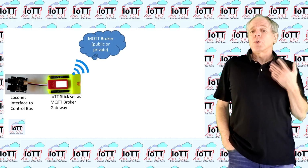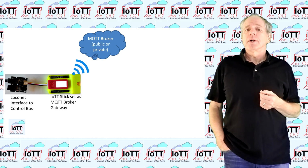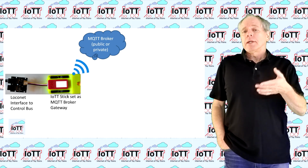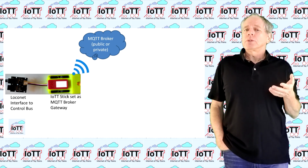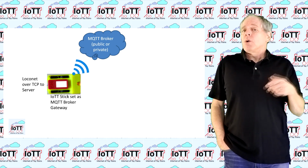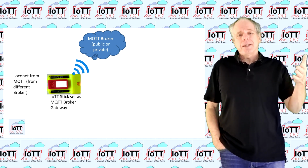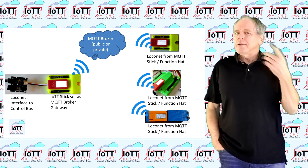The second option to connect IoTT sticks using Loconet is connecting them to an MQTT broker, similar as it is the case with DCC. The node that bridges between the upstream Loconet and the broker is called the MQTT gateway. It can be connected to Loconet using a Loconet interface, or as Loconet over TCP client, or it can receive the commands from another MQTT broker. Either method works, but you need to make sure to maintain the tree structure and not accidentally create a loop where messages could go round and round forever.